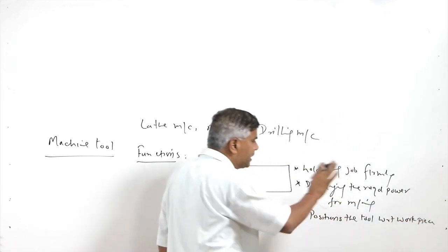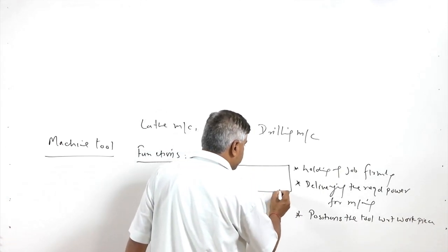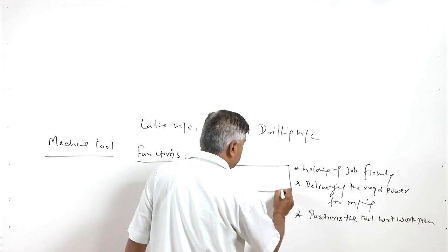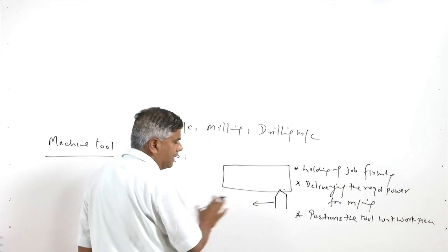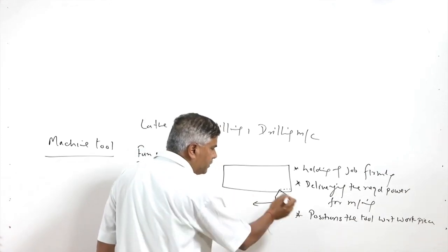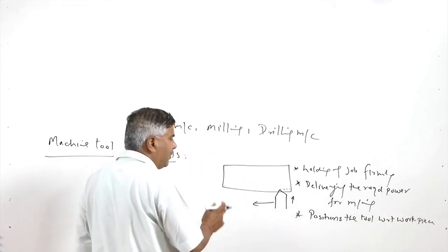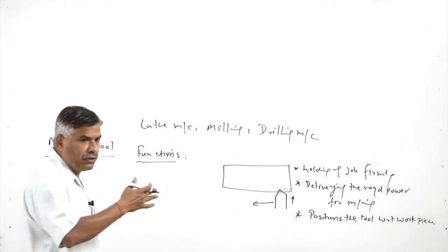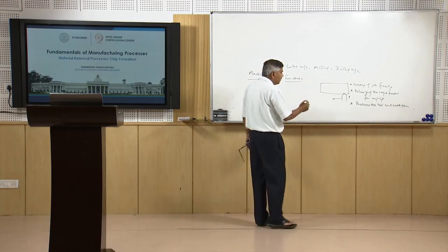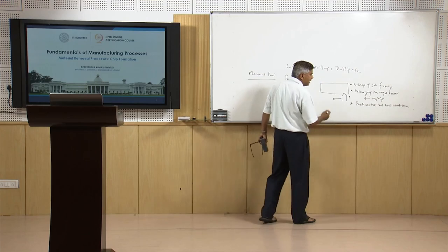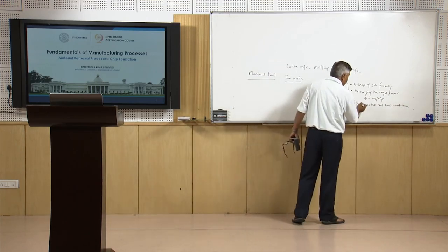and that position is maintained in such a way that, say for the turning process, the position of the tool is maintained at a particular position and it is moved linearly. If the position of the tool is not stable, then the geometry of the workpiece surface will not be as desired, and the roughness and dimensional accuracy will be badly compromised.